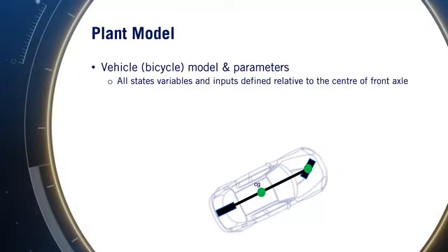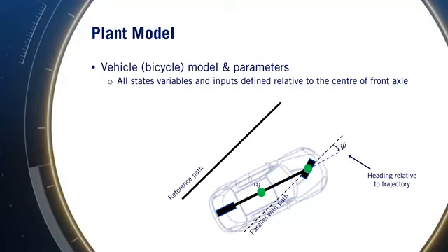a single drive wheel. For this discussion, we'll use a line segment as our reference path, shown as a solid black line in the diagram. A dashed black line that is parallel to the path but runs through the center of the front axle is also visible. For the purposes of lateral control, we redefine our heading relative to the current path line segment. The variable psi will be reused to represent the relative heading angle of the vehicle with respect to the path line. The front wheel velocity v and the steering angle relative to the heading direction delta did not change and are also shown in this diagram.